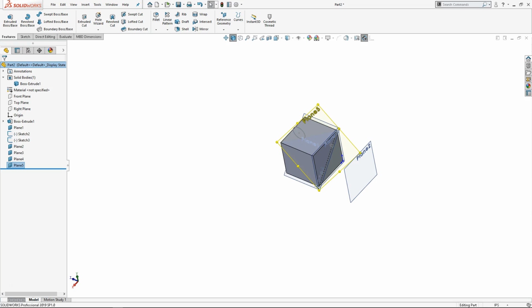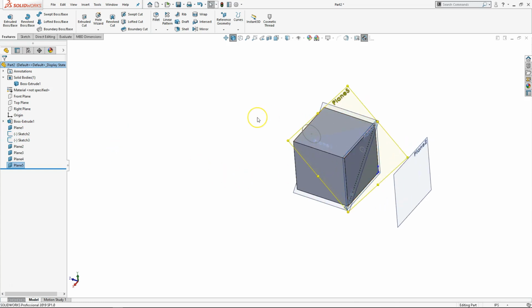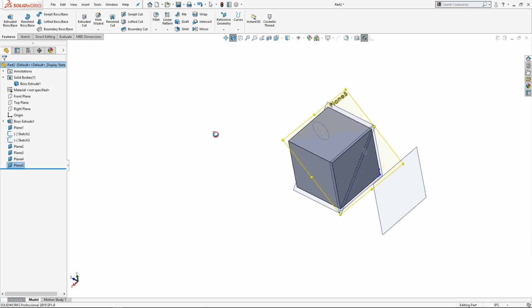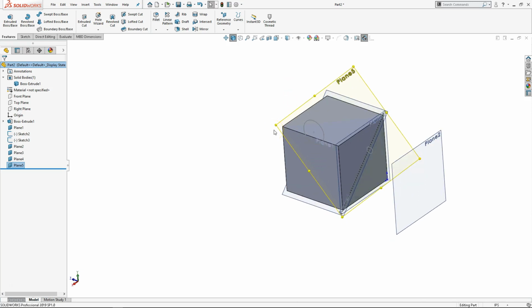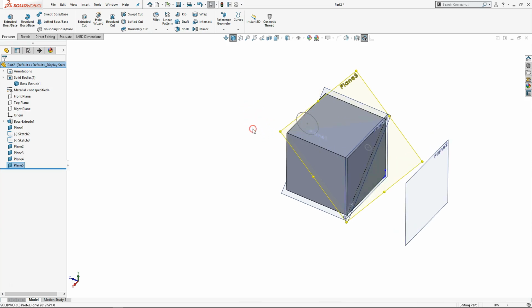Top-down, and hopefully I have my top-down example, is what I did with the pulley that I'm working on for the lander drop. And it was a quick way of making the geometry, but it comes with a lot of external references that I have to manage. And then multi-body or master model, as terminology says, that I can build multiple solid bodies and relate them together in this sketch, and then output them as an assembly or as separate pieces of geometry. So once we go through that process, then we're going to have these multiple shapes, these multiple references. Oh, the plane, I forgot one.